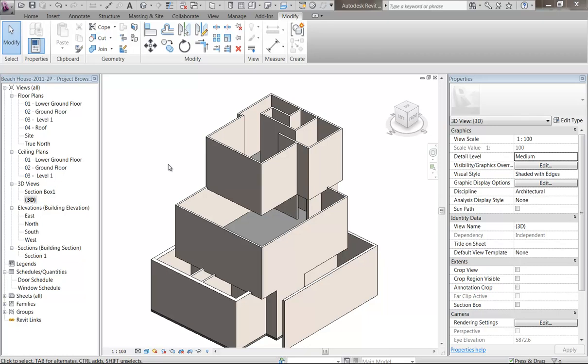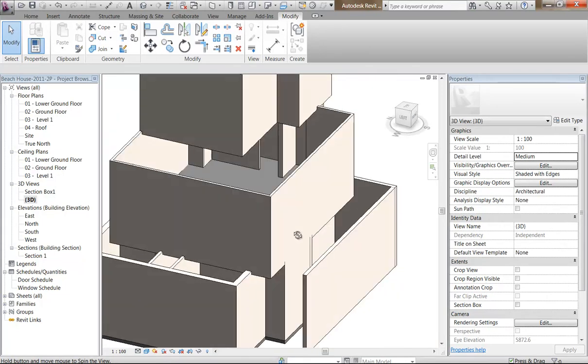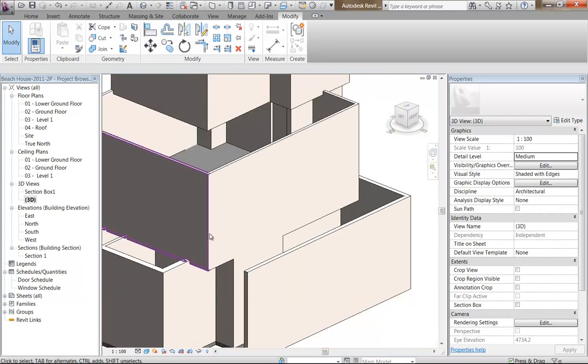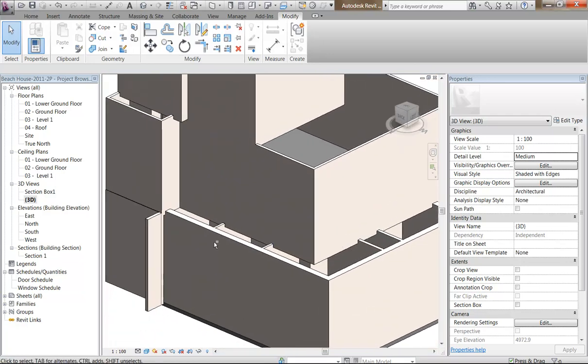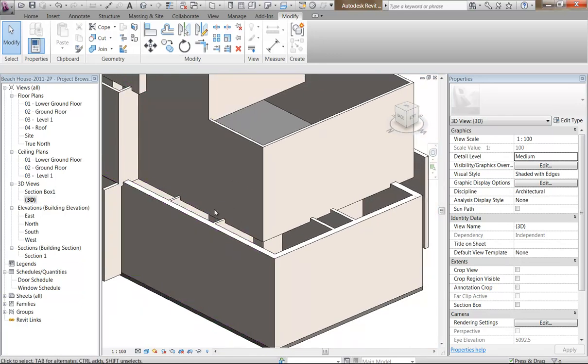Okay, so I've got the floors in, and most importantly, I've started to modify the walls so they work a bit better across all the different levels. And it is really important that you get that organised first before you go and start trying to work out your roof. Particularly when it comes to the walls and the floor where they join along the side where you've got the glass roof.